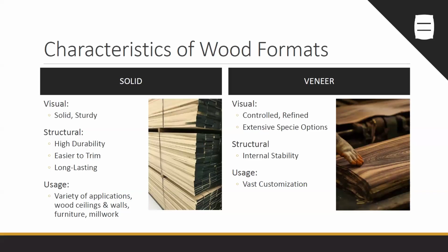Veneers are difficult to trim and work with on site. So the same scenario we just spoke about, if you had a veneer panel grill, once you cut the end of the panel grill, you're then going to expose the MDF core of the system. So not only are you going to have to seal it, but you also have to apply an edge band to it. So again, it's just a little bit more difficult to work with on site than a solid wood.